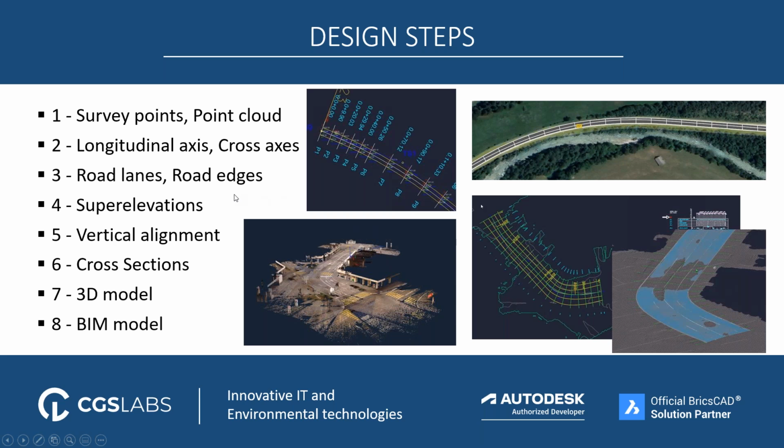Then we can also define the thickness of the new layers, from which we can also get automatic calculations of volumes. For the last part, we can create a 3D model with the cross sections and also attach it with some property sets to make it a BIM model.